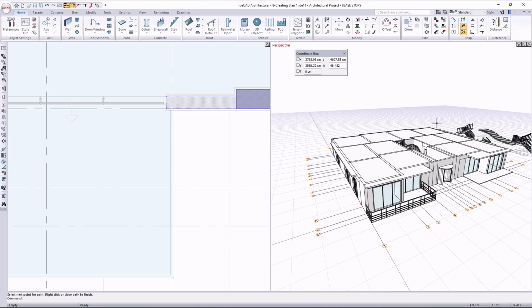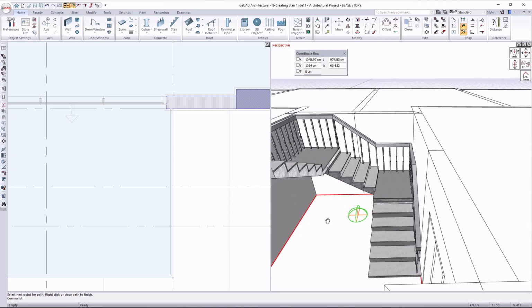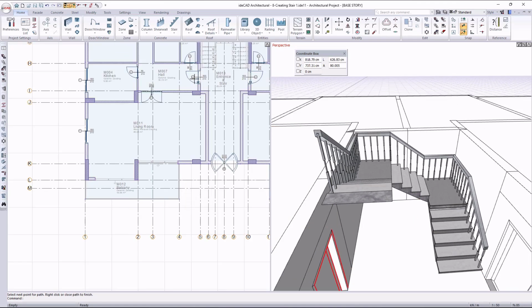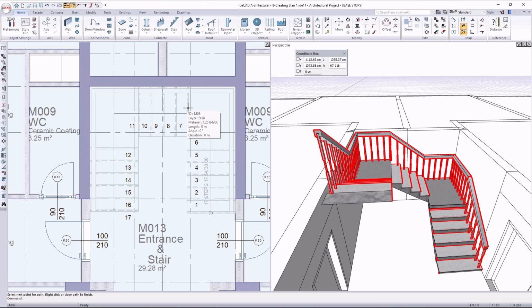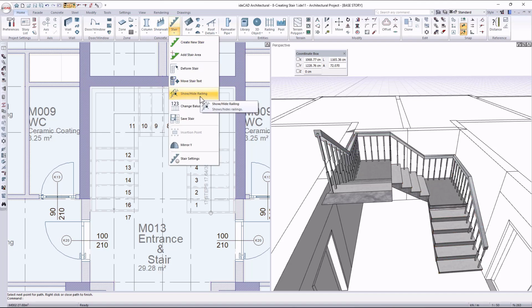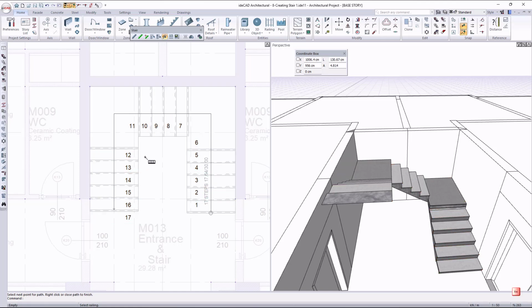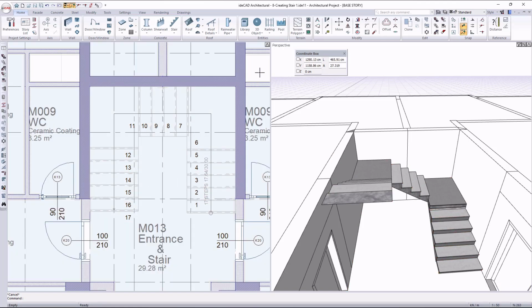Let's say the current stair railings don't match the desired design and a different style is preferred. In this case, the 3D Railing over Objects command can be used to define new railings for the stair. The new railing will be created directly on the existing stair. First, hide all the railings on the stair using the Show Hide Railing command. We'll use the 3D Railing over Objects command, as the railing is not being placed flat on the ground, but instead follows varying elevations along the stair.